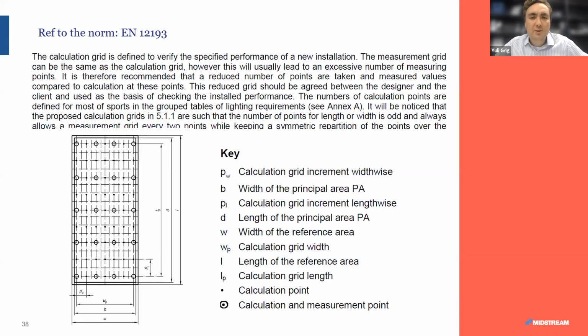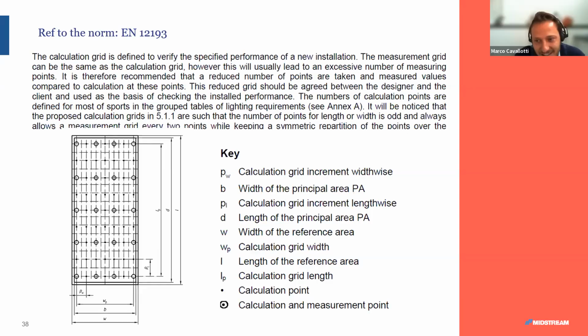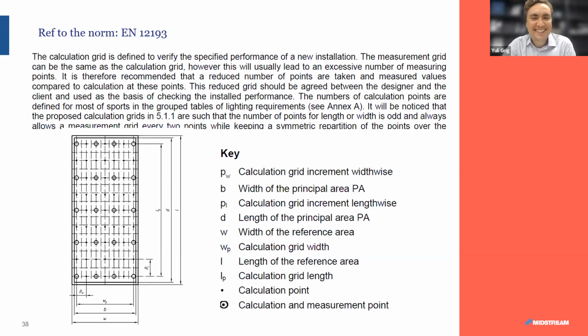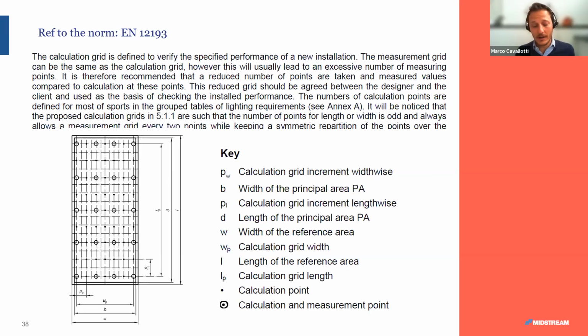So engineer Cavallotti, are you saying they should upgrade the sodium to LED? They should upgrade the sodium to LEDs as soon as possible. We always suggest not to mix two sources for two reasons. One is at the beginning in the design, because it's hard for a designer to evaluate the influence of an existing system together with a new LED system. This is the first reason. The second one is that the effect on the ground will be a mix of colors and technologies, and that won't be best practice for an apron in particular.